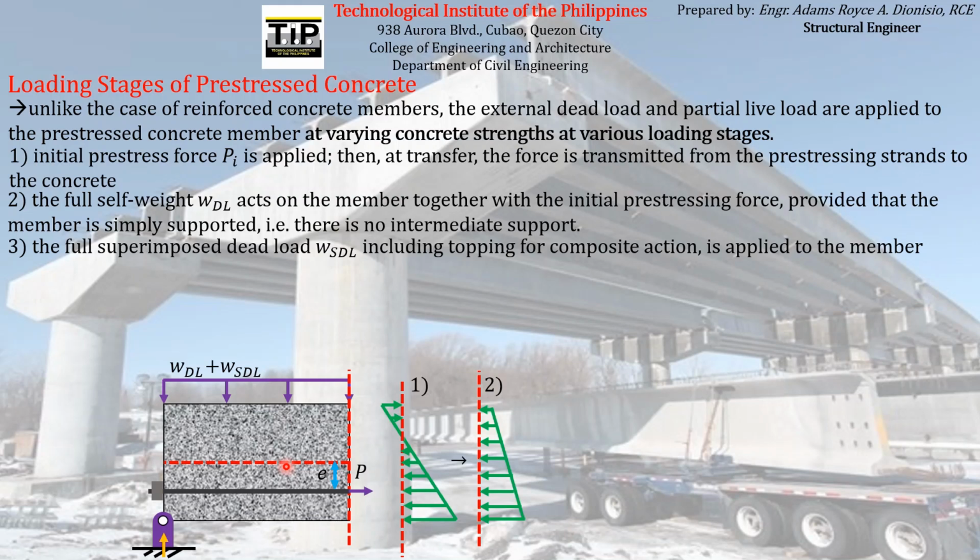That will also induce flexural stresses, which are compressive on the upper zone and tensile on the lower zone with respect to the neutral axis of the concrete element. If you again add those flexural stresses to the current stress diagram acting on the concrete element, the diagram will now look something like this.